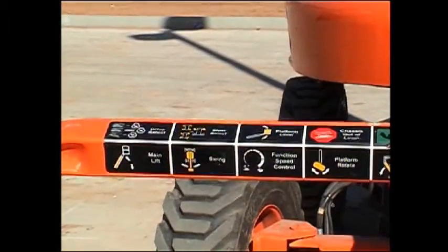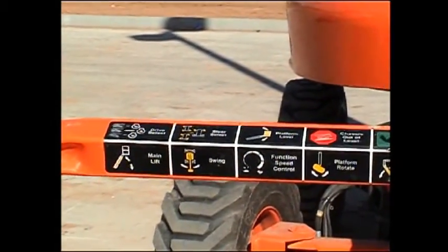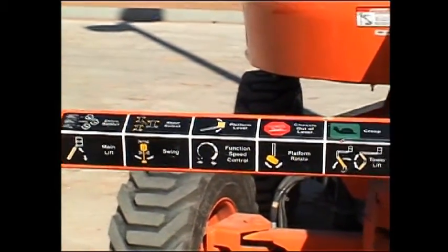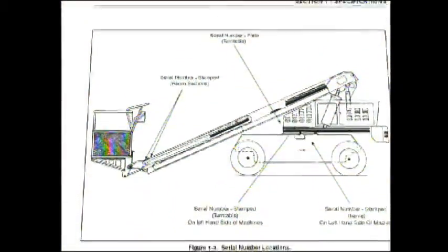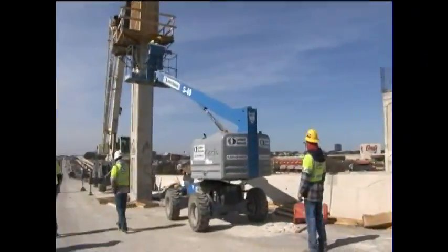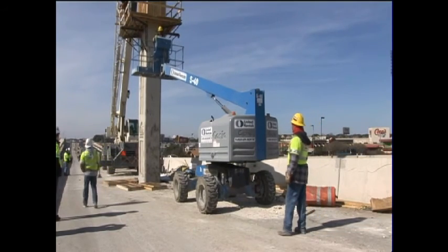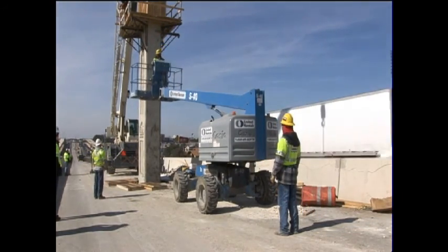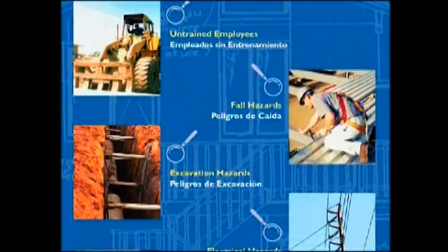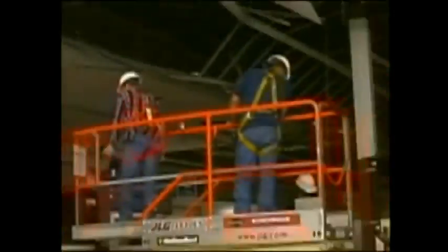Most lifts are equipped with various safety features. Never remove, bypass, or use these safety features for any reason other than specified by the manufacturer. Never modify a lift without written permission from the manufacturer or other qualified entity. If modified, the lift must be at least as safe as before modification. Employers should also be aware of local and state regulations and ensure compliance with those laws.